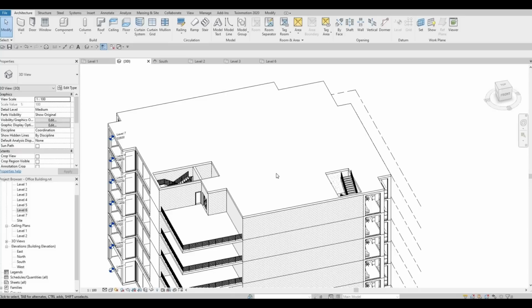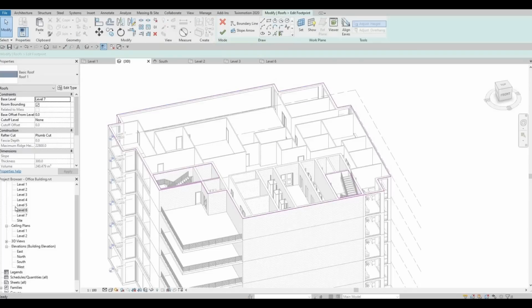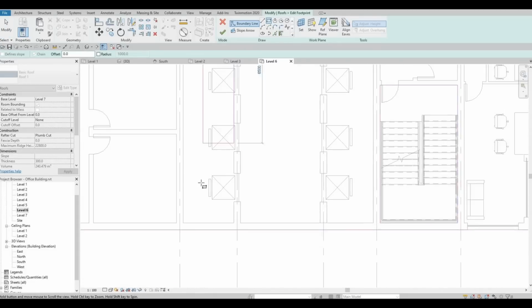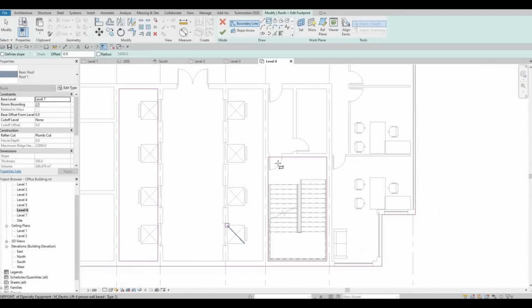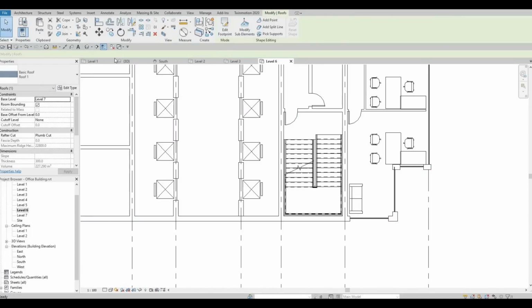So actually we need to open up some of the lift as well here. So I'm gonna edit this again and go back to level 3 and open this area. So I'm gonna open it like that and open it here as well. Click finish.